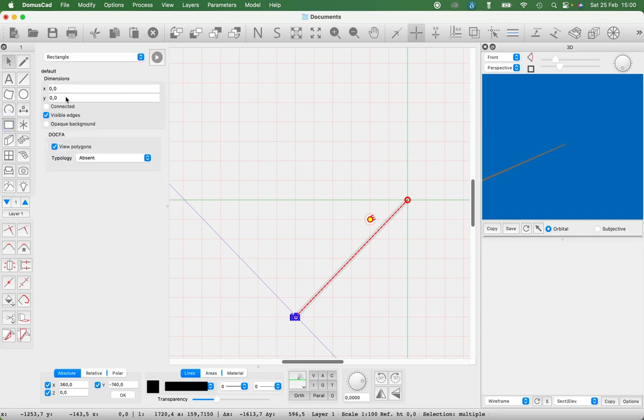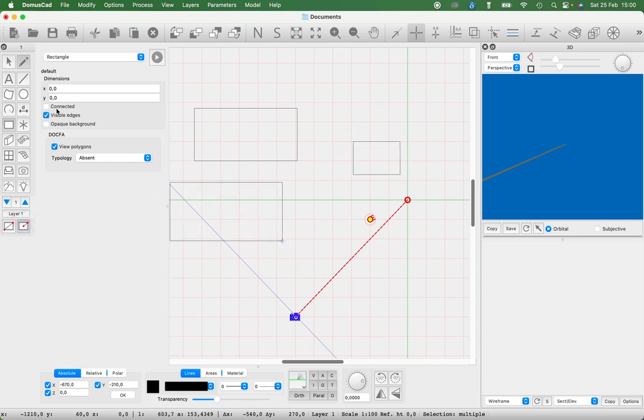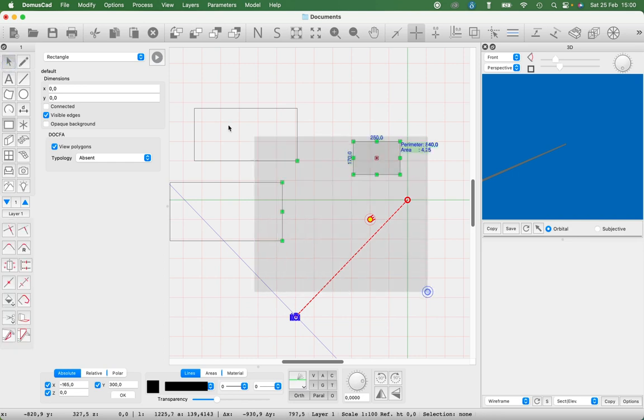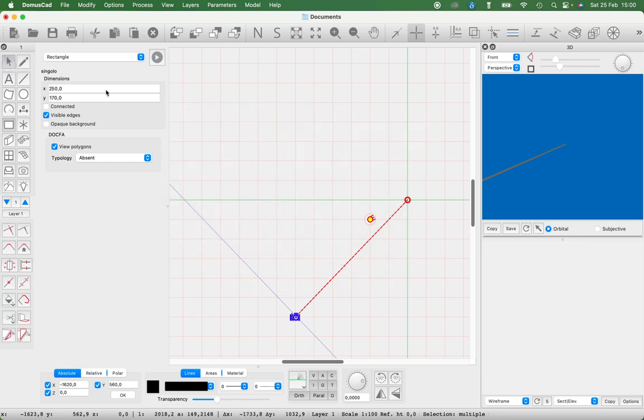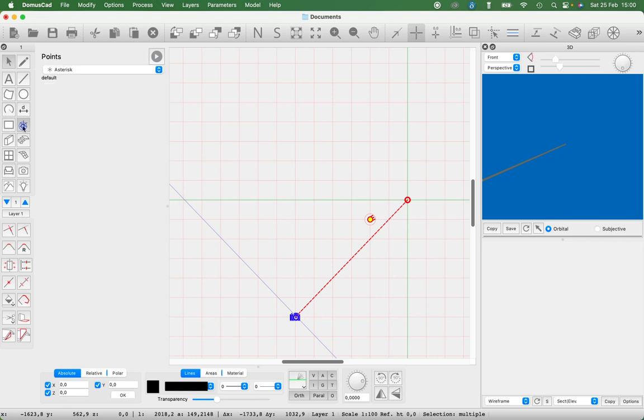The rectangle tool is used to insert rectangles, parallelepipeds and pyramids. In the first insertion mode, the diagonal of the rectangle is traced with the mouse. In the second way, the semi-diagonal is drawn, starting from the center of the rectangle. The markers are inserted in a simple way, with a click on the drawing.